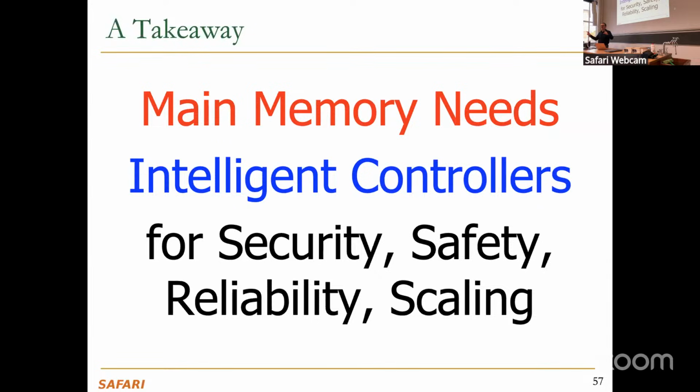Absolutely yes. Because if you want to keep track of rows, exact activation counts of each row, then what you need is really a content addressable memory, and it's expensive, basically. Or some sort of associative structure in the end, because direct map doesn't work very well in that case. But basically, the overhead is expensive, and the BlockHammer paper shows that. So it's cheaper. The trade-off is basically you don't keep track of rows exactly, but you get false positives. But a solution like TRR can also be... Exactly, yeah. So there could be things in the middle. So it's good to think about that.